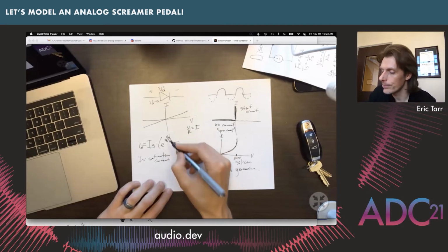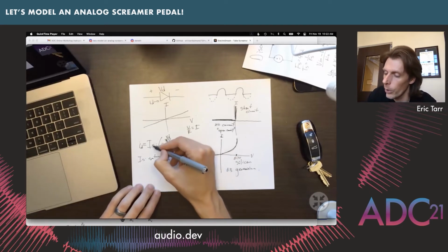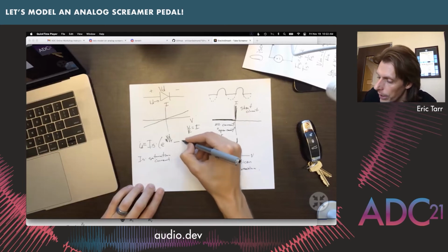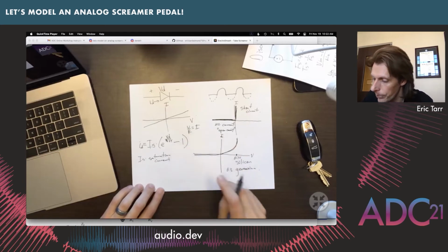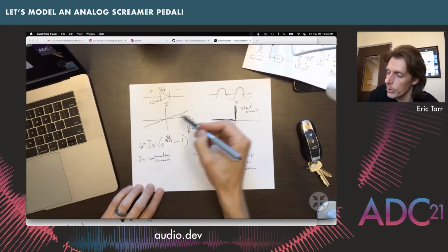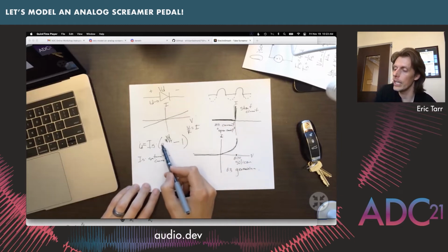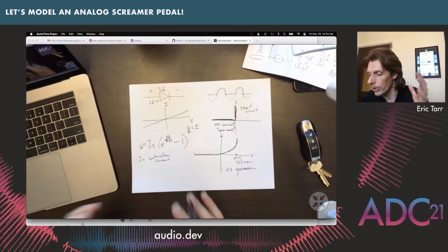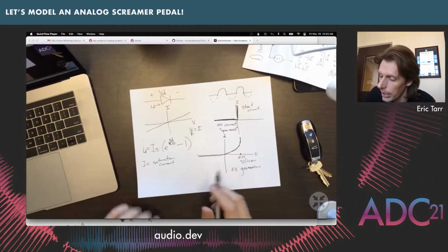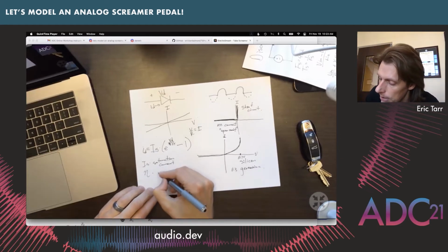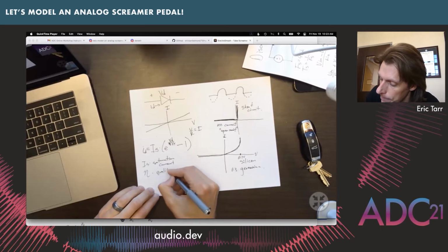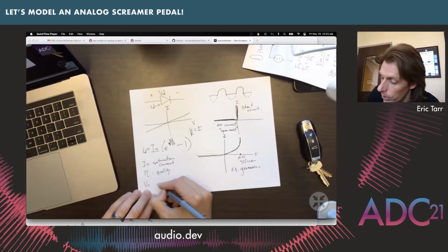And these are ones that we can adjust, but there's common ones that we will also find. And this whole thing minus 1 will give us our relationship now between voltage and current. So we have this nonlinear part of it with e raised to the power of this stuff that we have to deal with. Eta is this quality, and VT is thermal voltage.